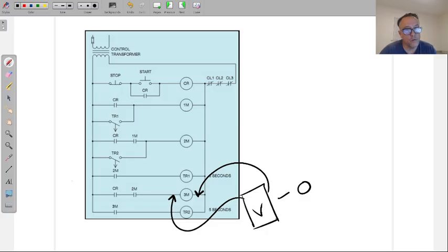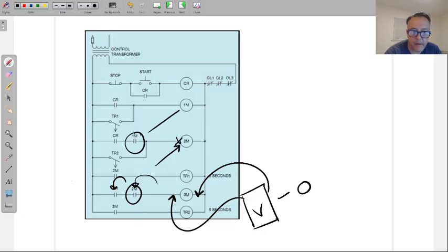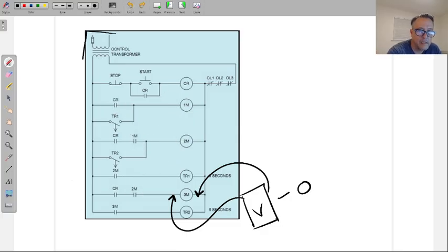So you can do this in one of 2 ways. You can go here and see if you have voltage, and then you can go here and see if you have voltage, and work your way. Well, 2, let me go check 2 to see if it has voltage. Nope. 1, let me go check 1, nope. Let me work my way that way. Or you can simply go, all right, let me check to see if there's power even coming into this circuit.